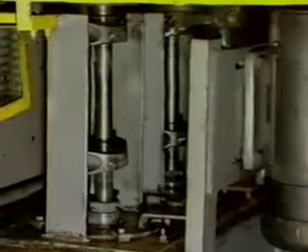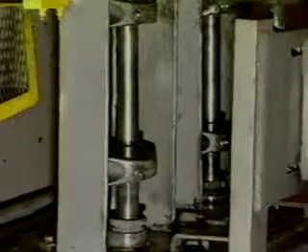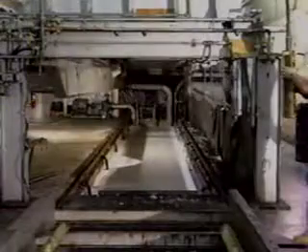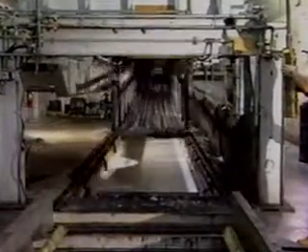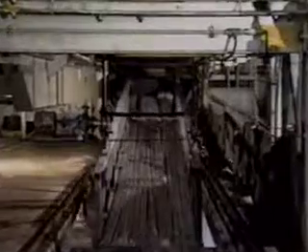In many cases, the impeller is encased in a tube which acts as a pump with the potential for directional control. These arrangements are called draft tubes. For example, multiple draft tube agitation is used for this elevator quench system. Another common configuration is the pit quench. A pit quench system often utilizes a draft tube agitator, such as this one.